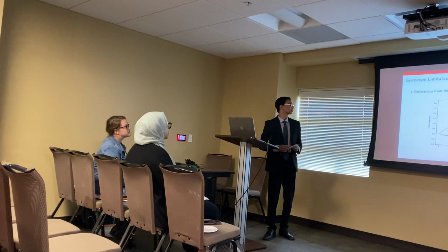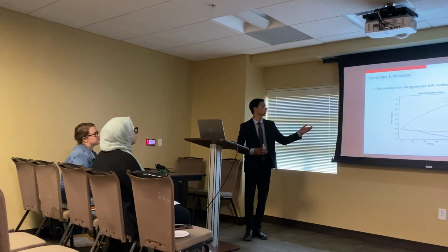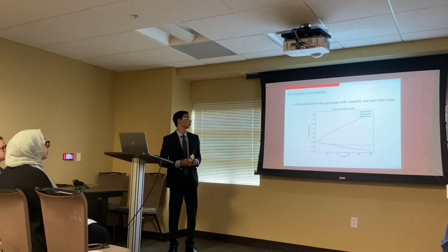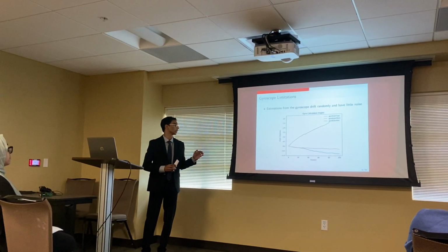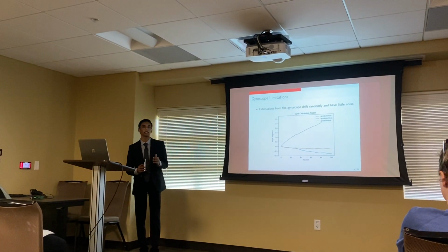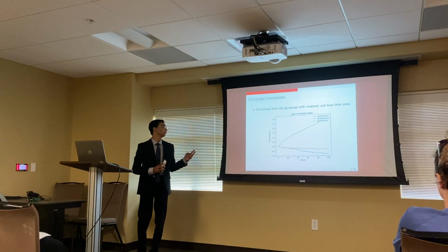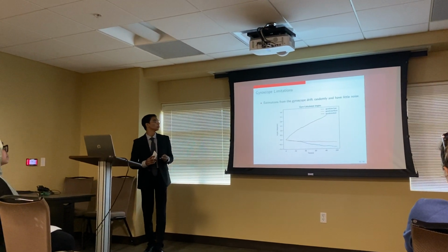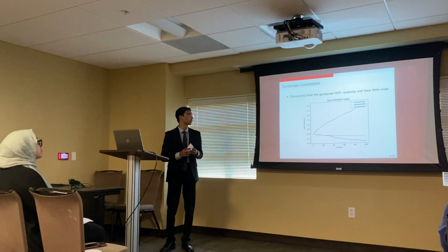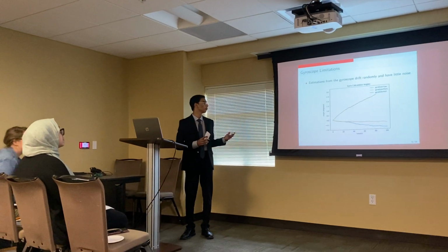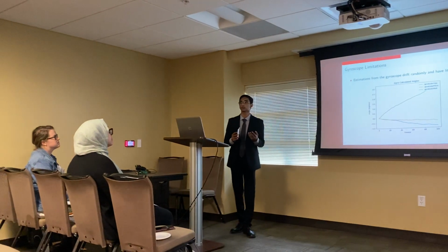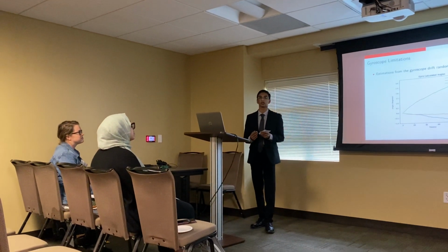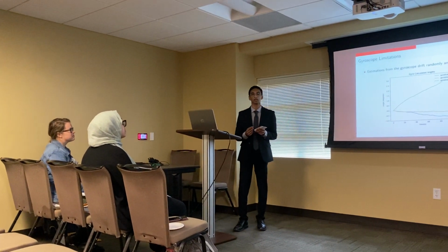So the gyroscope sensor is not perfect. Here you can see I've graphed each of the components of the Euler angle over 100 seconds for a stationary sensor. And we can see that all three components drift in random directions and with random magnitude. So we can see that although the measurements have very little noise, they drift over time, and that makes it extremely hard for us to obtain accurate estimations of the attitude from the gyroscope alone.